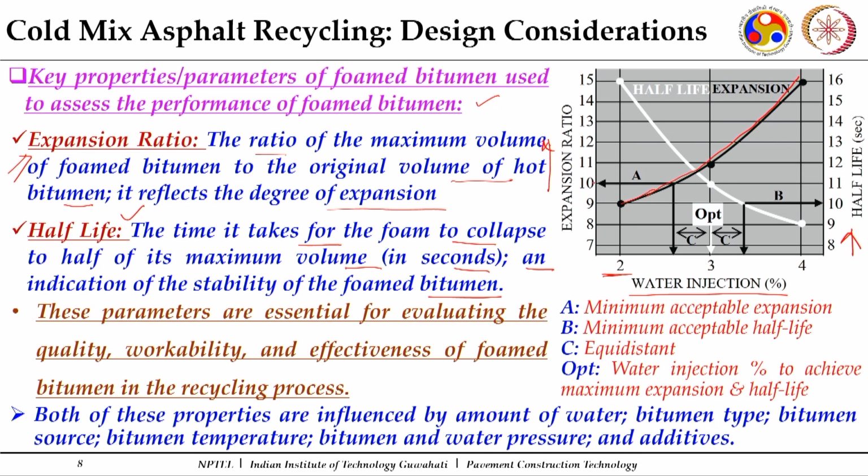Our target may be around 8 or 10. So here I am showing a target of around 10 times expansion in the volume. Simultaneously, the half-life goes down as the percentage of water injection increases. This white line shows the half-life, and my target for half-life is around 10 seconds.